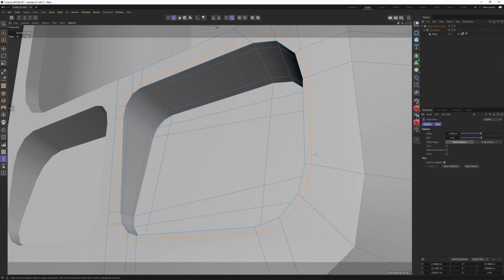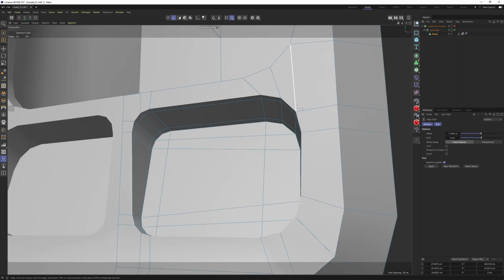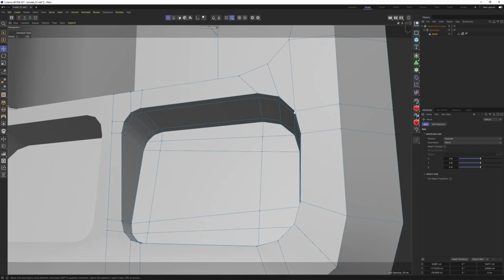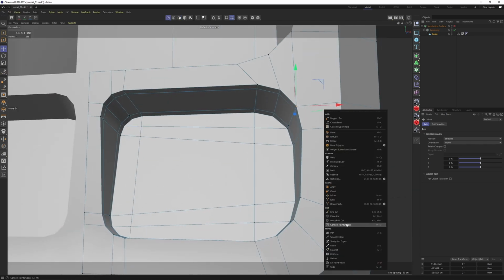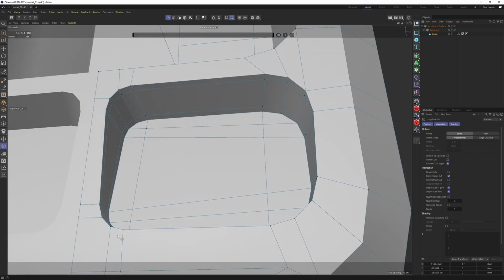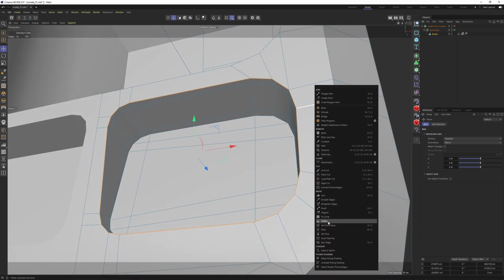So this is very similar to loop cuts, but loop cut will not work because the boundary is not in a good shape. I am talking about this, for example, n-gon over here. Then there is a pole. So if you want to add a loop cut, it's not gonna cover the boundary. As you can see, because of that pole, it's gonna go straight up. And if you check this one, because of that angle, it's gonna stop right here. So in this kind of situations, I like to use slide tool.